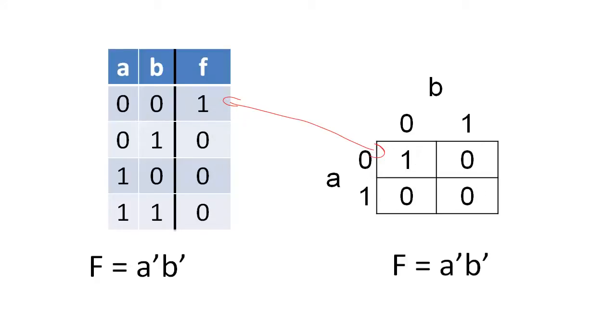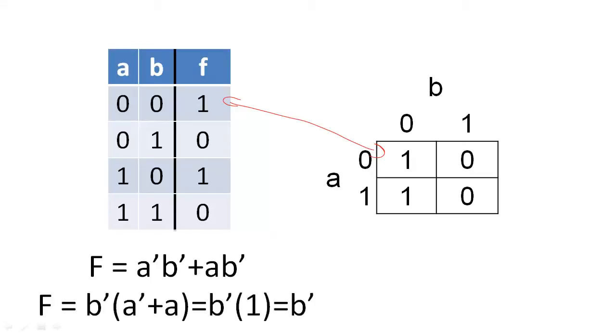The advantage of the K-map for optimization is that it creates a visual representation of some of the Boolean identities. For example, if we had a more complex function, we might translate the rows with ones into a Boolean expression. We could then use a series of distribution, complementarity, and identities to derive the minimal solution. This series of identities works because the two minterms differ by only one literal. The K-map maps corresponding minterms in a way that each cell differs by only one literal from its adjacent cells.